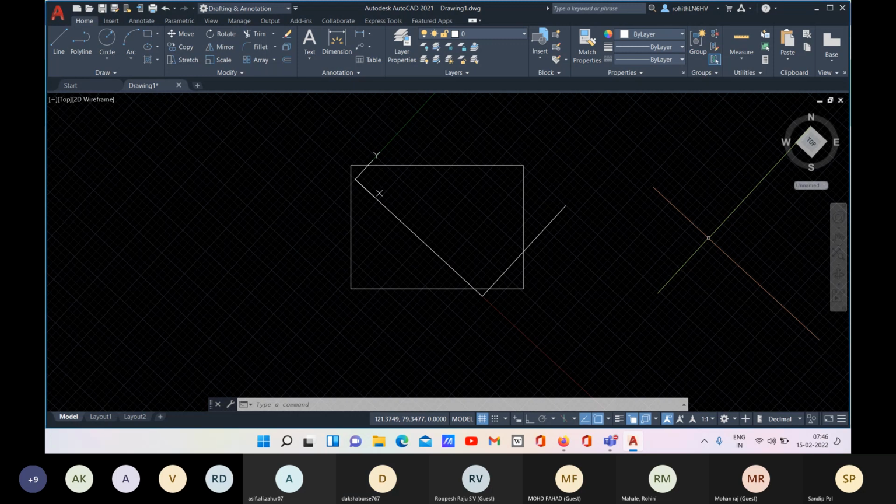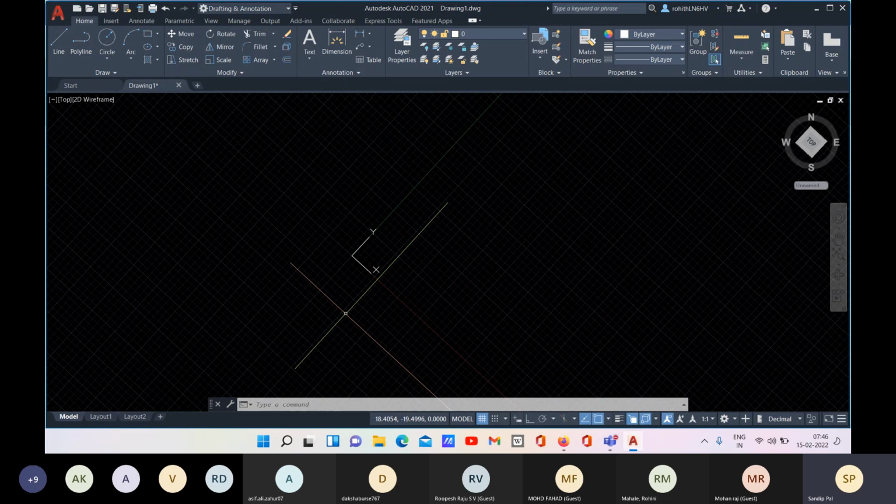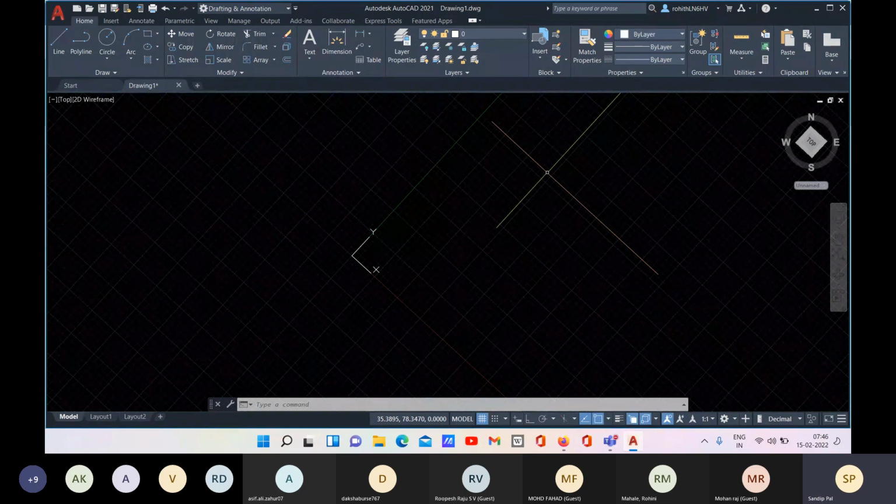Yes, sir. Okay. So now you know that all the default values are for UCS, and UCS is the default coordinate system in AutoCAD. But we need the result as per the WCS all the time, and we won't place the star all the time for that.